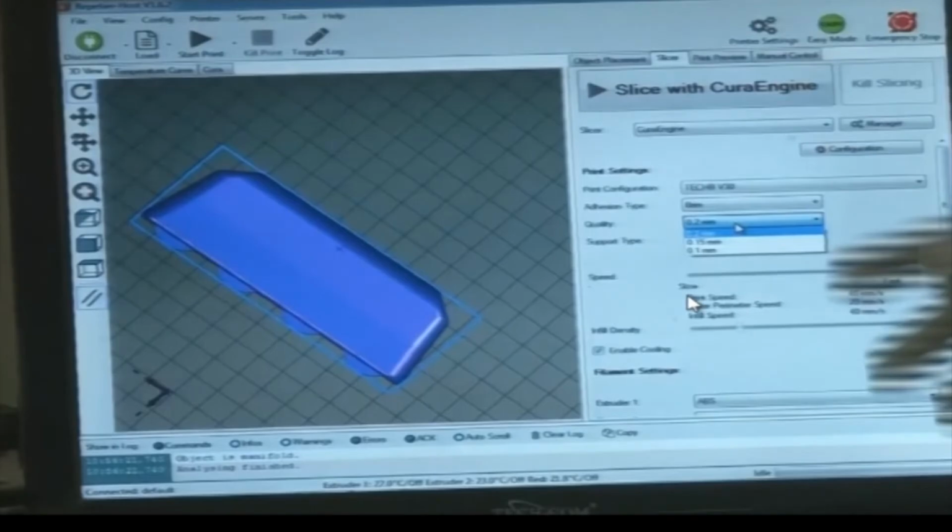And also, as I said, the quality and speed are countering each other. If the quality is higher, the speed would be lower, because with 0.1 mm versus 0.2 mm, obviously the speed would be 50% of 0.2 if I use 0.1, okay, because 50% of the layer size is being deposited at each layer, at each slice.